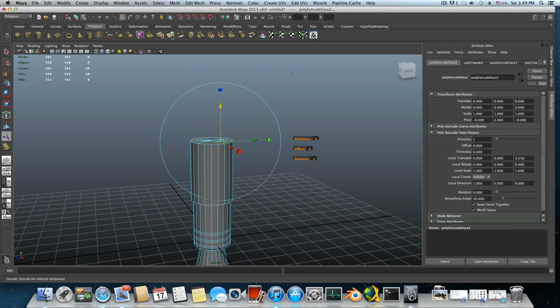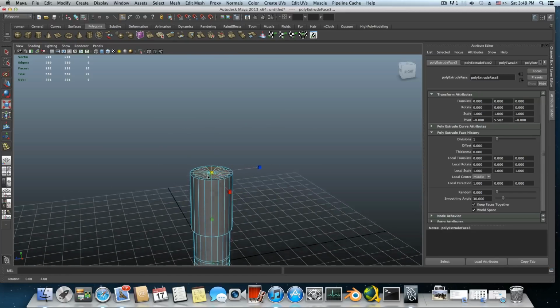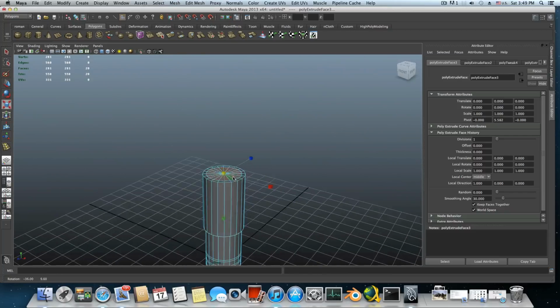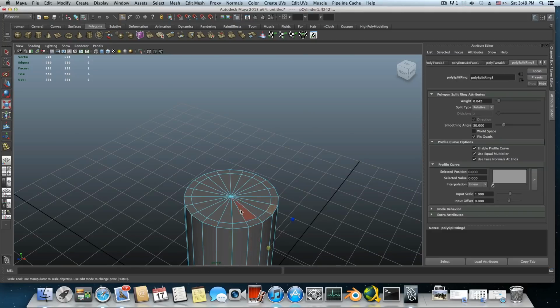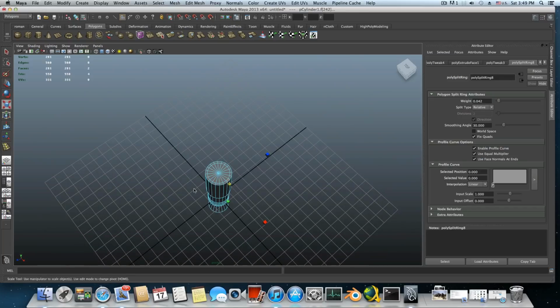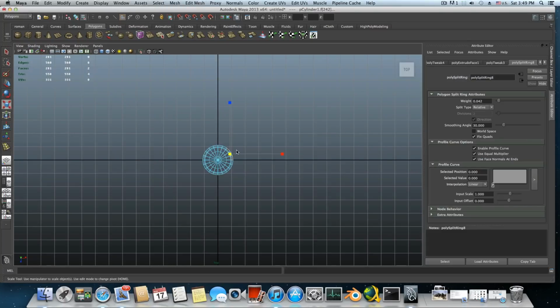Again extrude, and this time I will use the scale tool again after applying the extrude and try to match it. So see this here, those faces here will be the same size as these. Now in order to do this you can change to four view by clicking here and then put your mouse cursor over the top and press the spacebar to expand it.